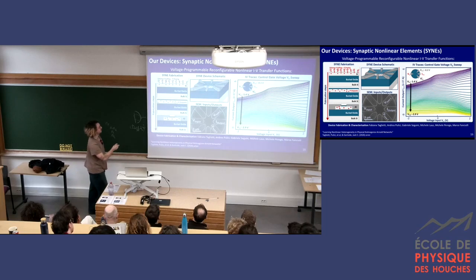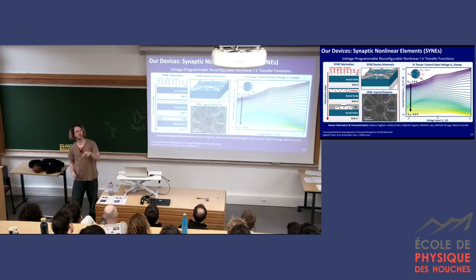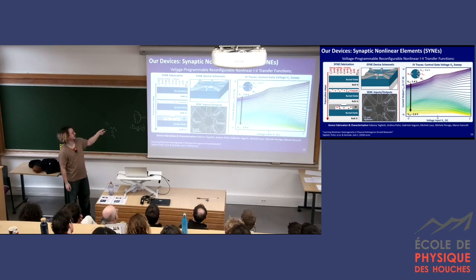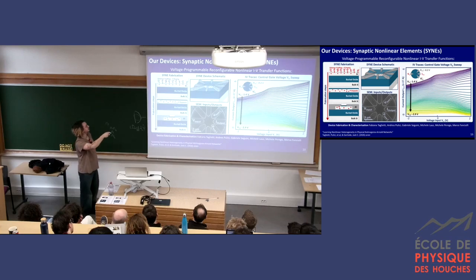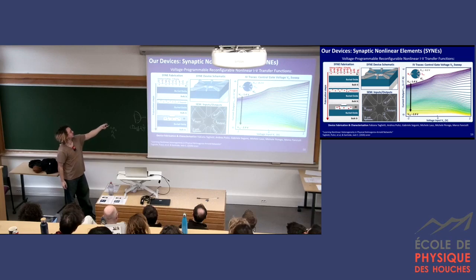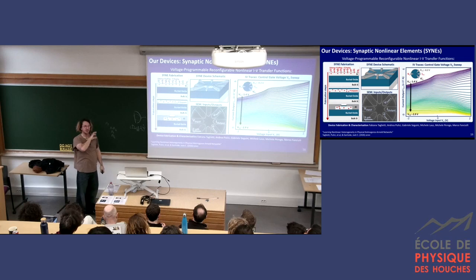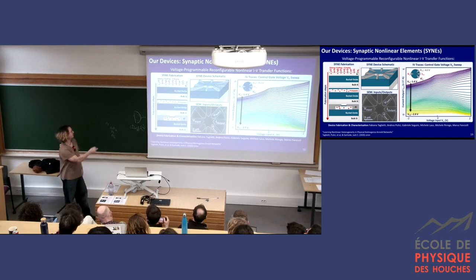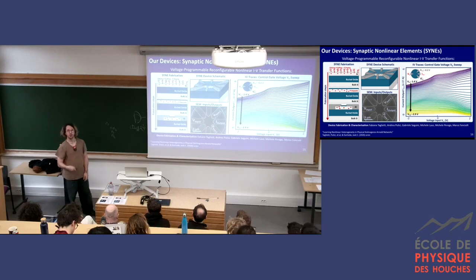And we came onto these. So I was at a conference a little bit like this in 2024 in Erice in Sicily. There's another one this April, so if anyone's interested, it's a nice location, good talks come along. And someone was presenting just a kind of materials characterization talk, but they were showing these. So what they are, and this was Fabiana Taglietti's talk in Erice, you just take a thin 30 nanometer silicon layer on top of a buried oxide, this kind of silicon-on-insulator technology, and they use a cool technique of doping I hadn't seen before, where you take a polymer with your dopant ion on the top, and then you flash it in the oven for about 1 second, and you get this pretty disordered distribution of these dopants.